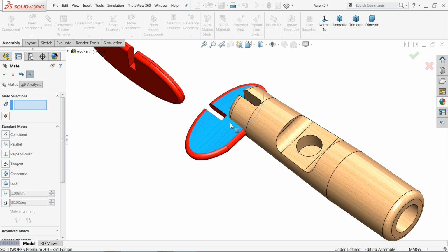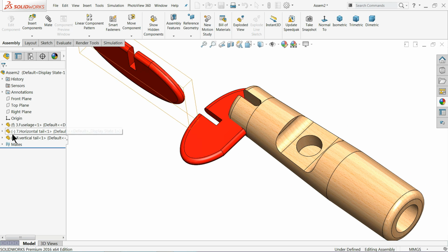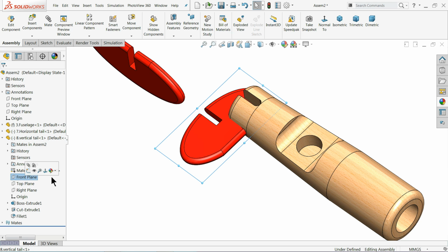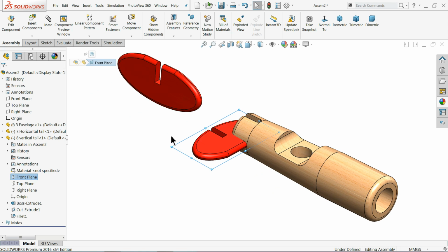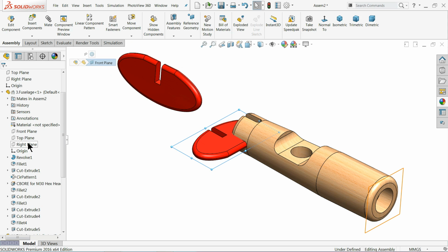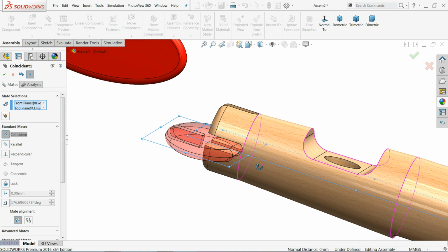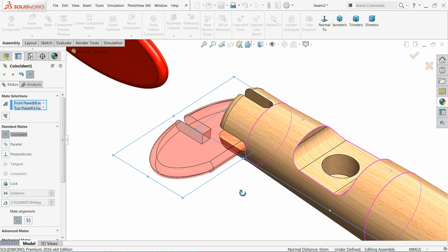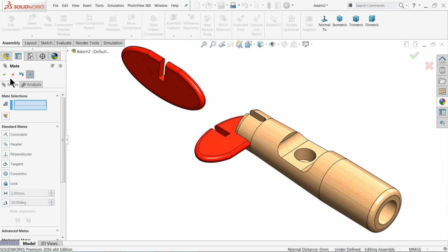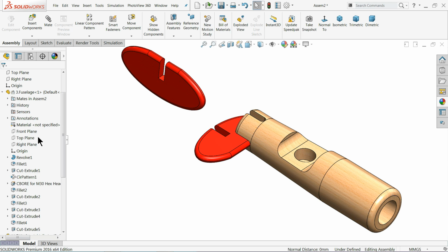Now you can easily move it here and there. So here we will create one more important relation, front plane. Now see, this is the front plane of this mate and the fuselage body. Let's say which plane it is going to mate with. Hold shift key, sorry, control key, and click here, mate, or simply select mate. Now see, it's in one line, in one plane. Okay. Now here we need to do one more relation.